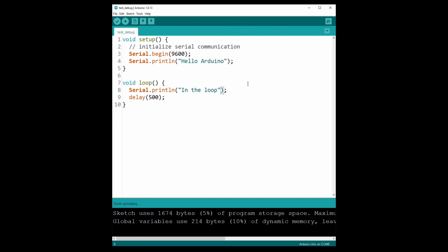All right, so to restart, maybe the easiest way is simply to press the reset button on the Arduino. Otherwise, you can just open and close the serial monitor. But note that this works only for some Arduino boards. So for example, Uno, Mega and Nano, it's fine. But other boards like Leonardo, this will not work. So the most universal way to restart from the Arduino IDE directly is you can simply re-upload the code. Okay, and this will restart the program.